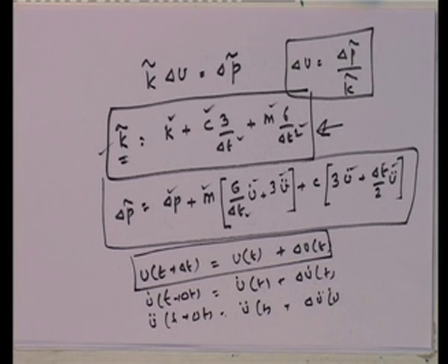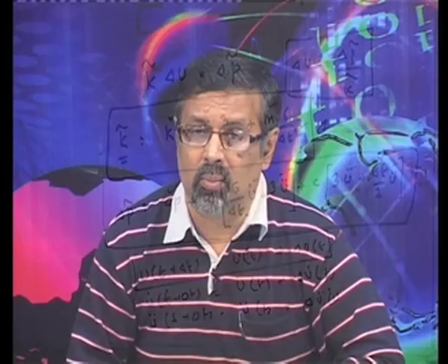The beauty of the implicit methods is that, as long as delta t is small enough, and I have already discussed what delta t needs to be, I do not need to go back. If delta t is small enough, this is always stable, because you are making an assumption on V double dot.